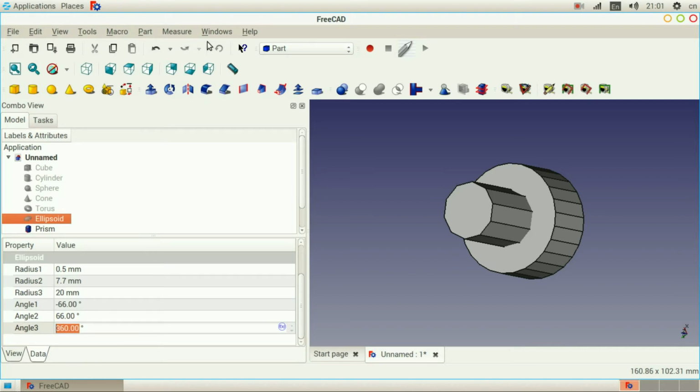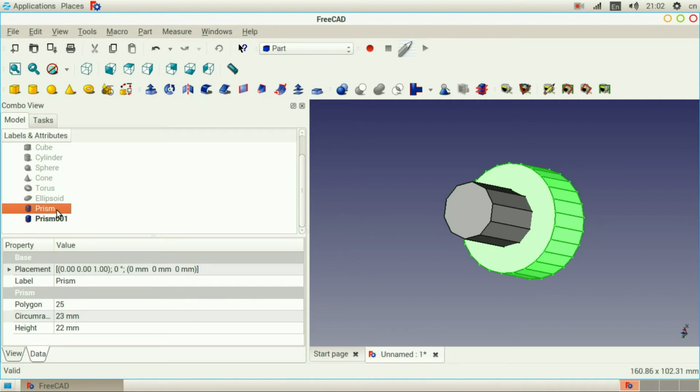Another common thing people may not do is use a combination of workbenches to do various things. Because this is very object oriented and you can use these Boolean operations across the board. That's very nice. So whenever you start a part in Part Design or something, you don't have to make the part entirely in that one. It would show maybe some skill if you did, but you wouldn't have to. And it's honestly better if one was to learn all the tooling and be able to effectively cross-platform it between workbenches.